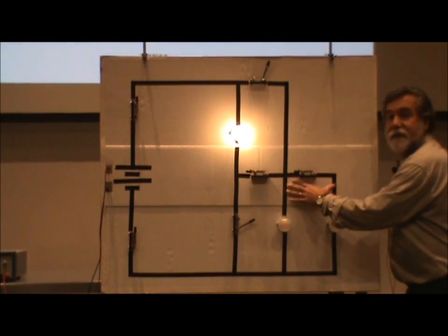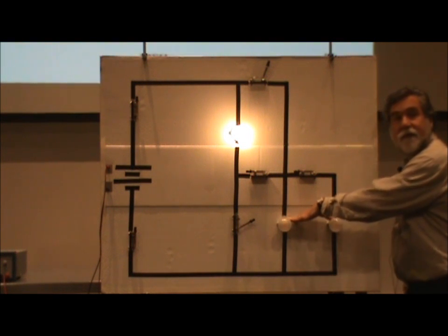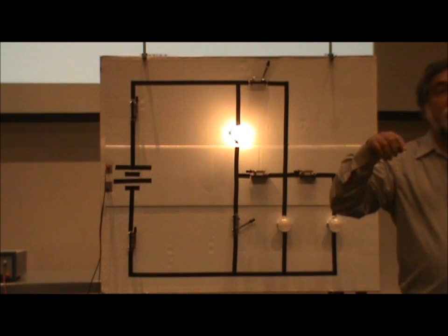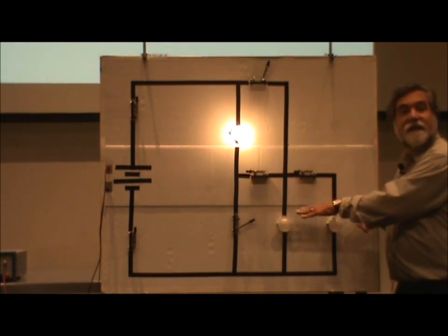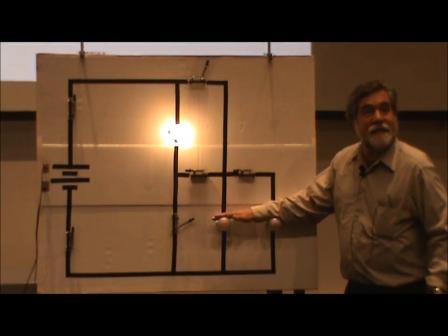what we've done is to put these 2 bulbs in parallel. When I did that, the resistance of these 2 bulbs in parallel must always be lower than each of the bulbs that make up the parallel circuit. Because they're adding up the inverses, it turns out when you add resistors in parallel, the net resistance is always lower. Right? So I dropped the resistance here.